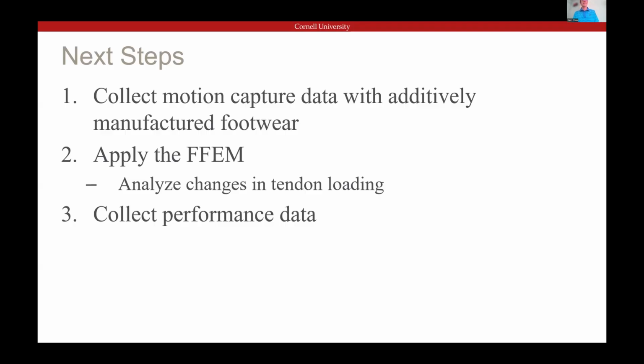Since we saw a lot of viscoelasticity with the shoe, it probably would not help you that much. It would be kind of like running on molasses almost. You'd be losing a lot of energy through it. It would be kind of difficult, but it would still be cool to test out the finite element model to see if it can capture that.